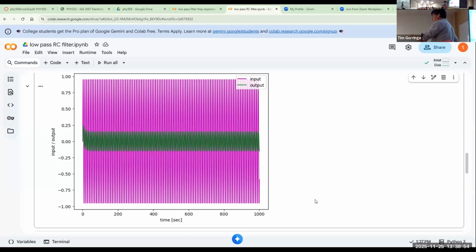And this is the problem that you had mentioned, actually, that we're making an assumption about the prior history of the input when we calculate the output on the first sample. And that assumption actually leaks into the future. You have a memory about that assumption that lasts for several time constants. And so this change over these first few cycles is this memory of our assumption about the unknown history of the input prior to the first time sample.